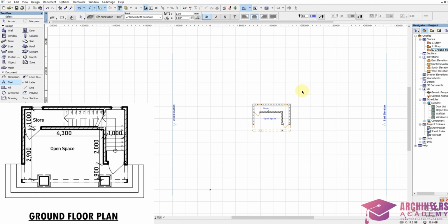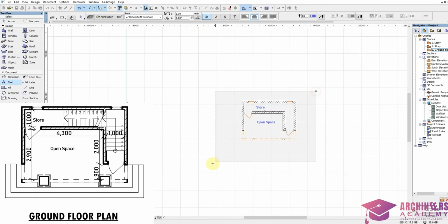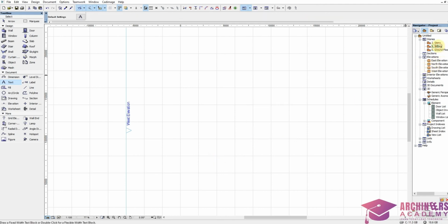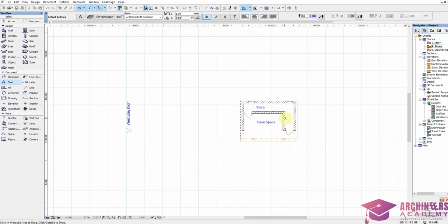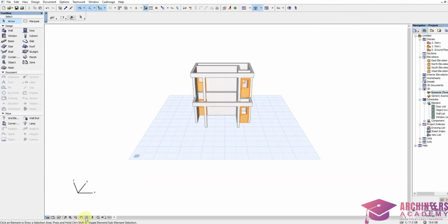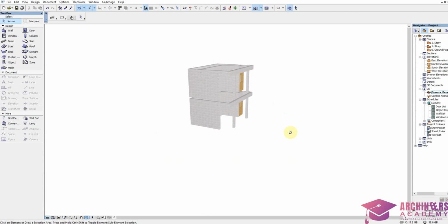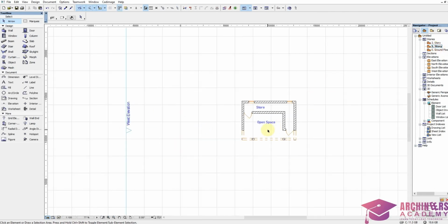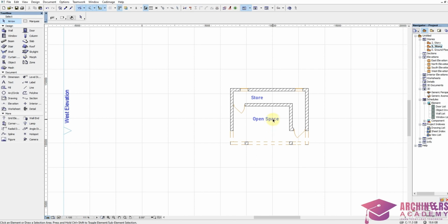Then to move over to the upper floor plan, we just highlight all these, click on copy, over to the first story and paste, Ctrl V. Don't adjust your screen or anything. Just once you copy and paste, click OK to lap properly on it. So this is just how it's done, just copy and paste. Then we can start editing this one now to suit our upper floor plan design.